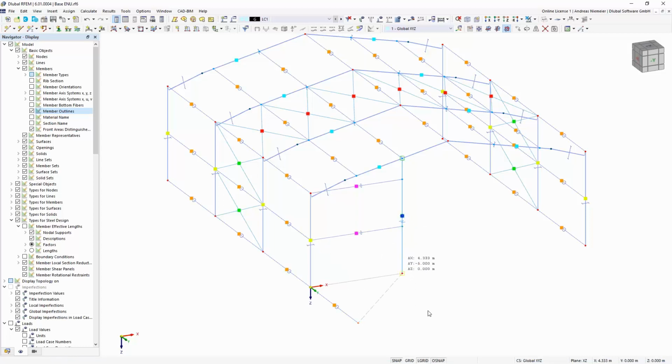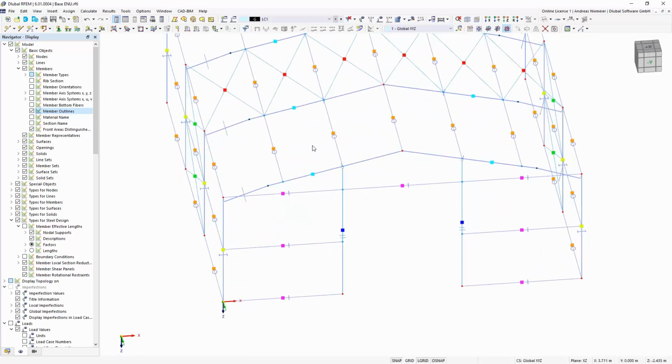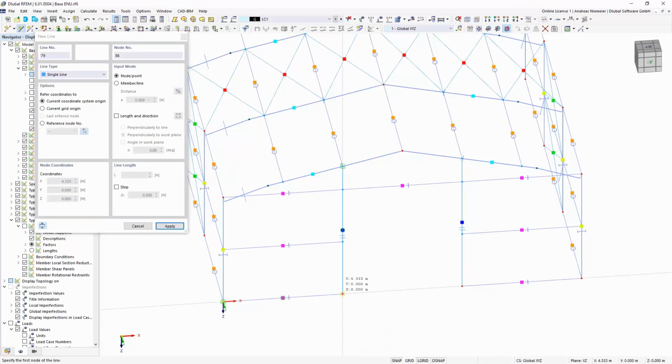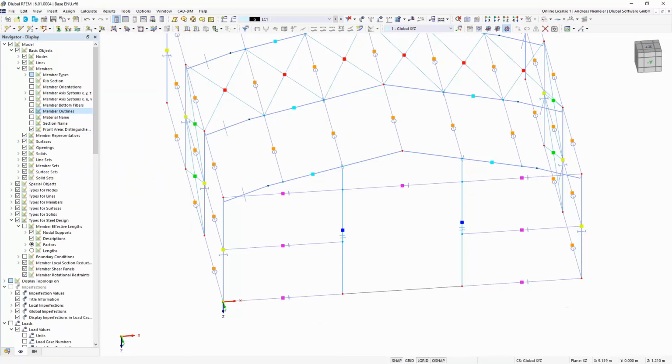Now we can close the wall like this. We copy again this column here on the other side. Take with a selection step the 3 horizontal members and now close the top with this beam. You see, this was quite easy to fill this wall with the right members, and now I only draw a simple line on the bottom but it has no statical or structural effect. It's only for closing. Why?